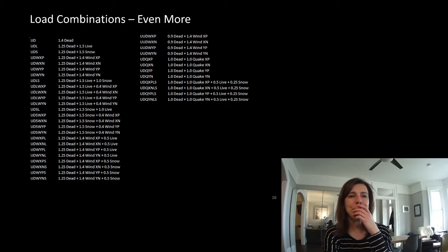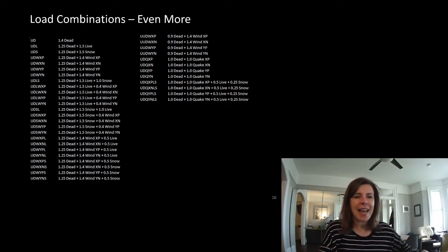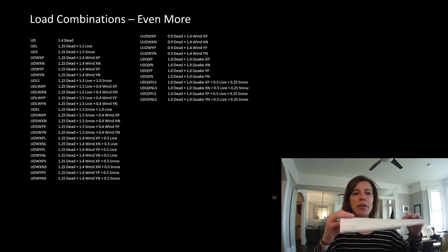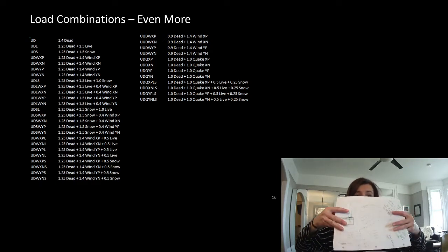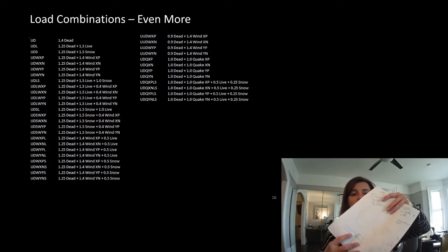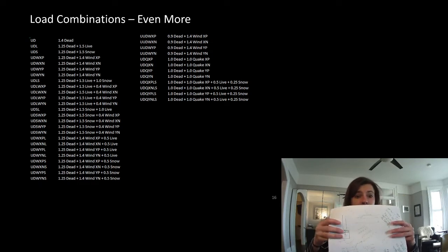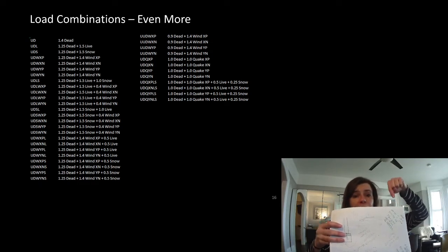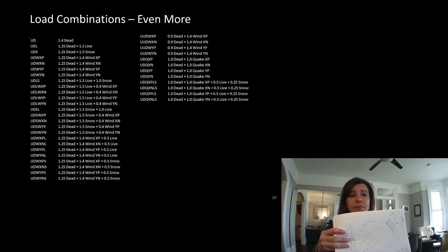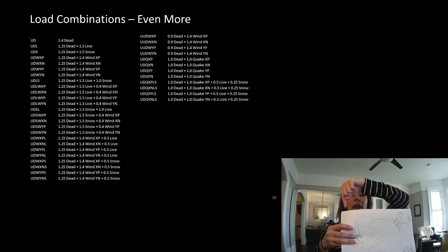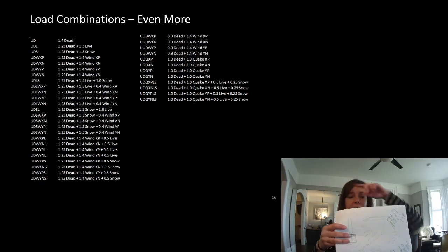And do you guys remember in our wind load, we had that end zone? And I said that end zone was all about, if this is the roof of the building that I'm holding up for you guys, it wanting to make the building twist. So we would have analyzed it with the end zone here, and then we would do another analysis with the end zone here.